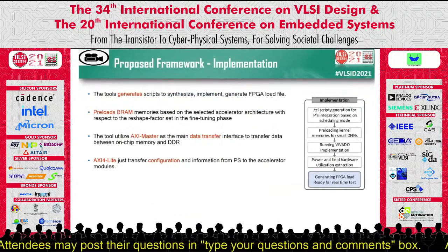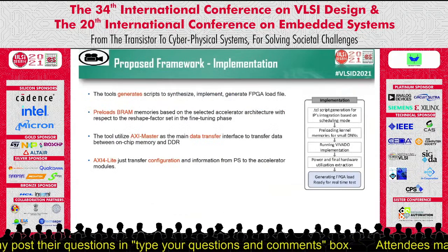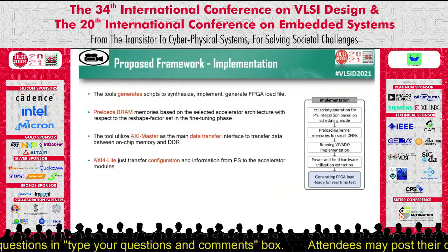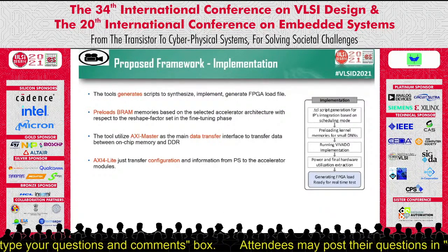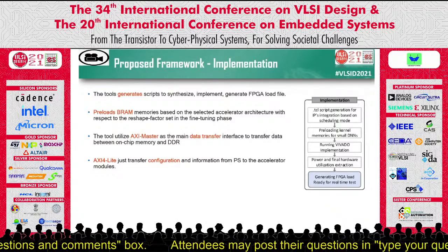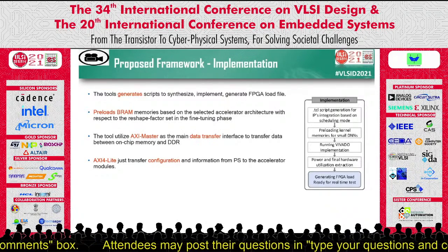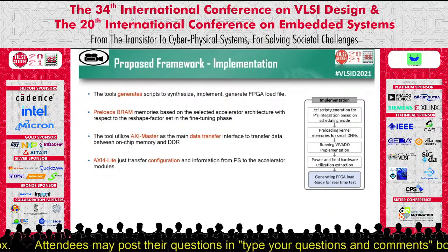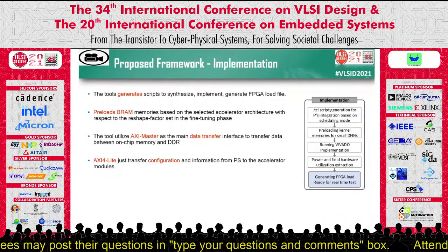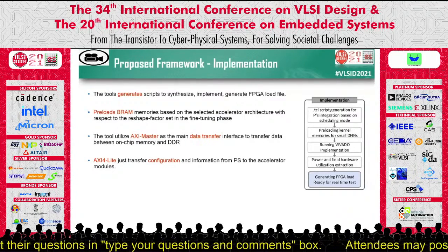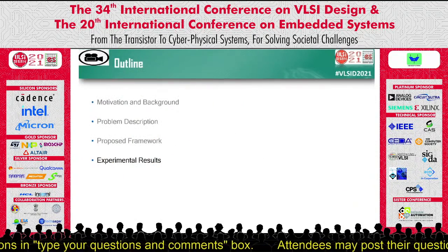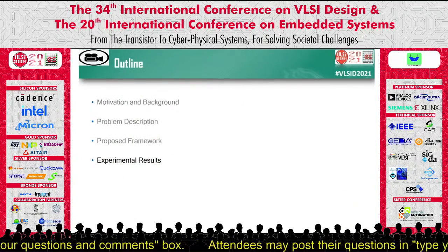The final stage generates the bitstream and preloads each BRAM memory based on the selected accelerator architecture with respect to the unroll factor in the optimization stage. The tool benefits from full AXI for data transfer and AXI Lite for configuring the PL side by the PS. Now at the end, the experimental results.